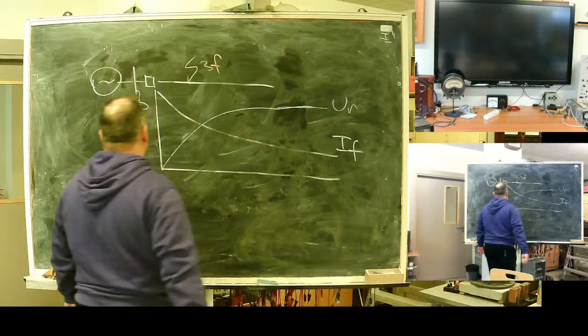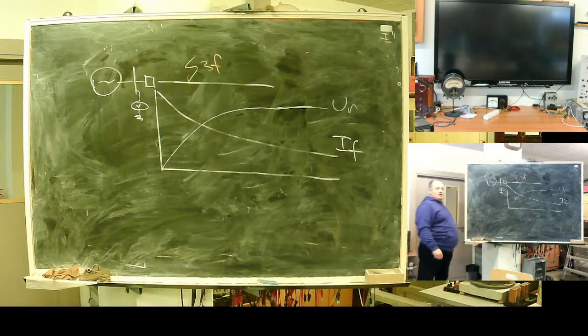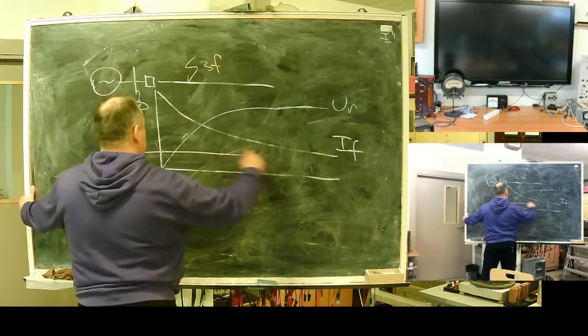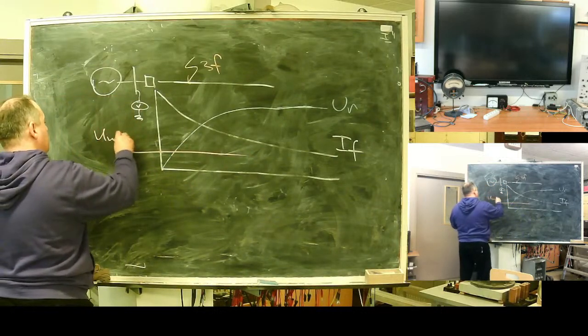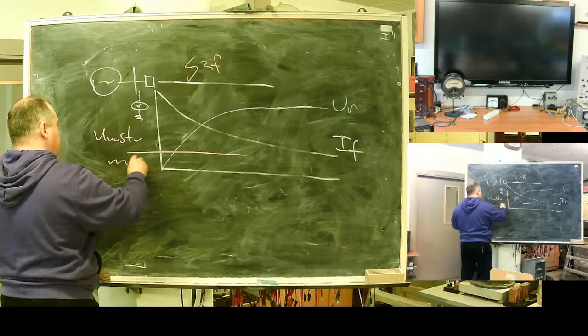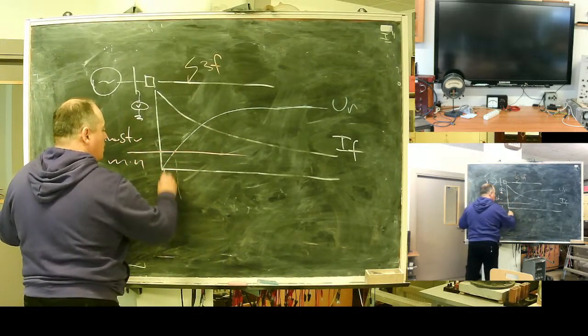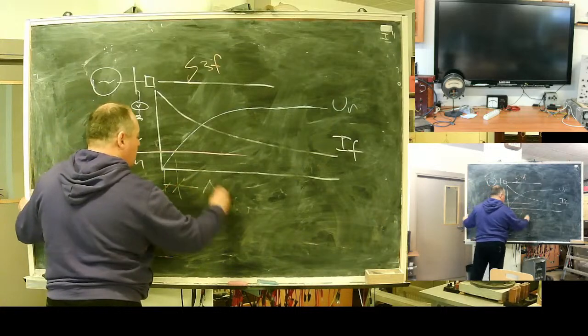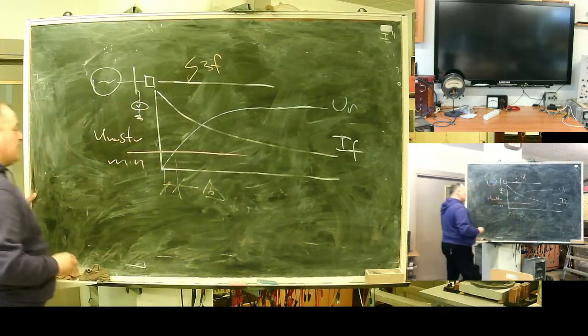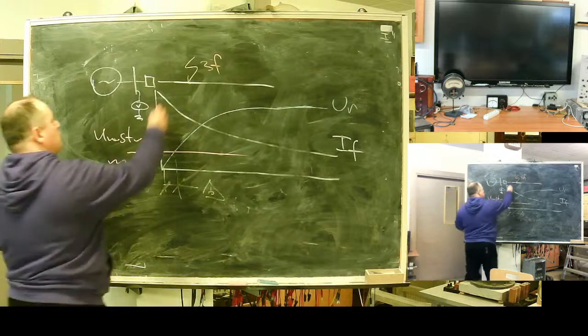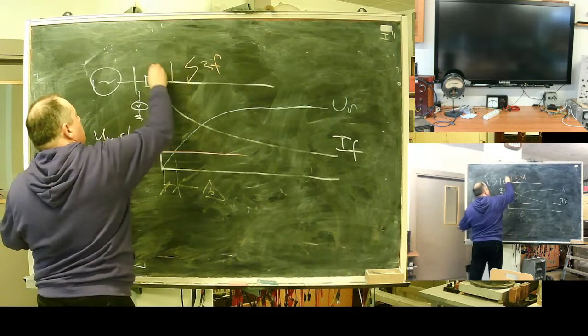This is voltage available to my relay. Draw a line. Minimal trip voltage, and what you will get, this is called blind zone. It's a part of line where, in case of three-phase fault, relay is not capable to detect direction. So this will be not protected.